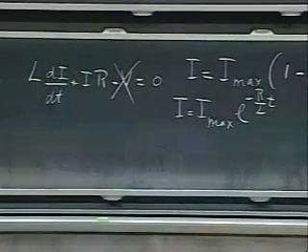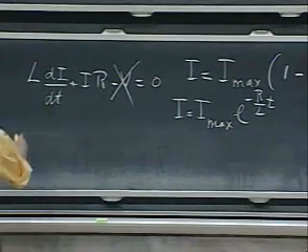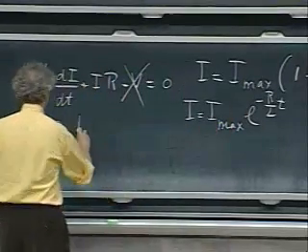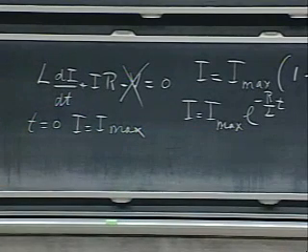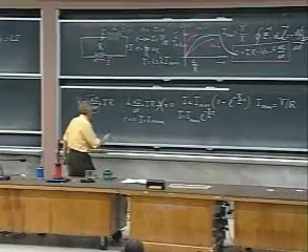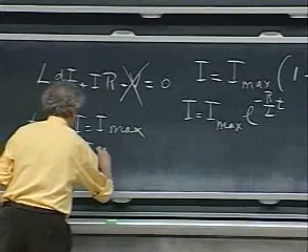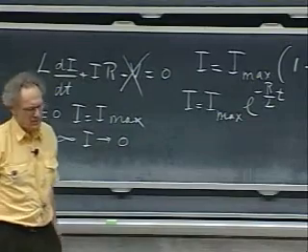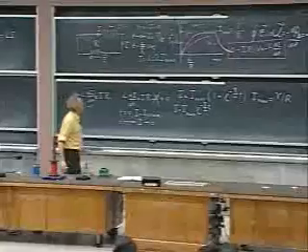And that exactly has all the quantities that you want it to have. Because notice that at t equals 0, when you put in t equals 0, the current is indeed maximum. And that's what you require. That's the moment that you make that capital V 0. The current was still running. But notice that when t goes to infinity, you wait long enough, the current goes to 0. And if you wait L over R seconds, then you are down to about 37% of your maximum current.